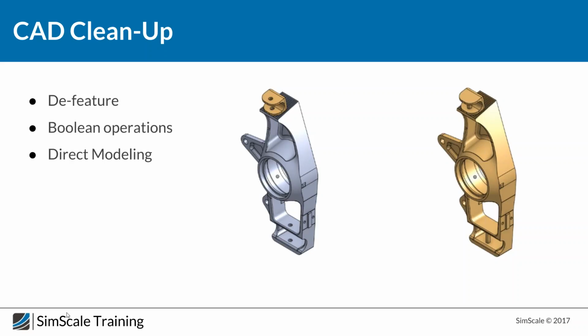But if I would like to consider them in my simulation model, it would blow it up. The difference between a model with all the screws and without the screws is very small in terms of result accuracy and result outcome, but the difference in terms of computational effort is gigantic. And therefore, we need to simplify our model. And again, as simple as possible, as detailed as necessary.